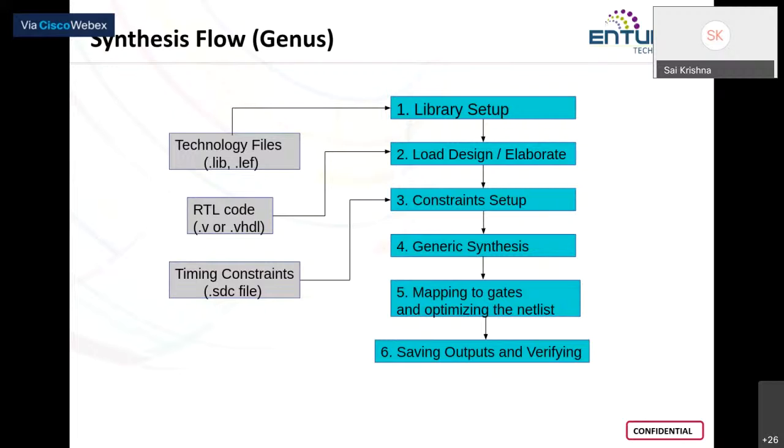Once mapping is done, optimization is done to remove the redundant logic, and whatever final gate-level circuit you have is recorded in the form of connectivity into a gate-level netlist. You will also have your timing, area, and power reports, along with block-level STA. So this is the recommended flow, and shuffling any of this will throw errors, so please avoid that. Okay, next.